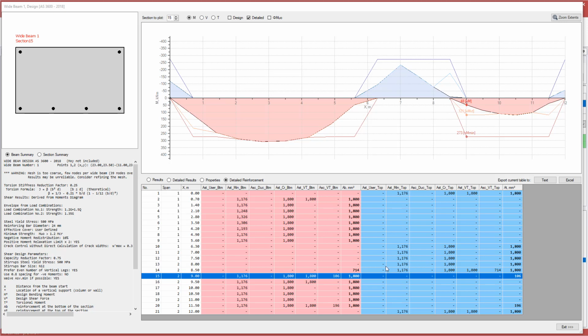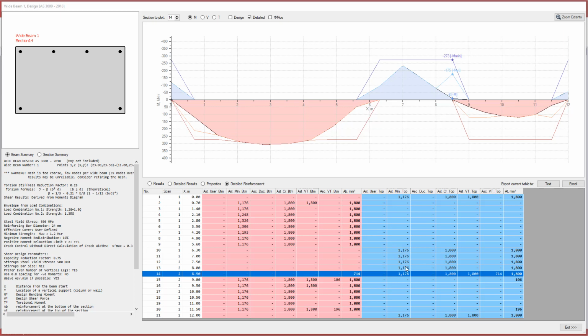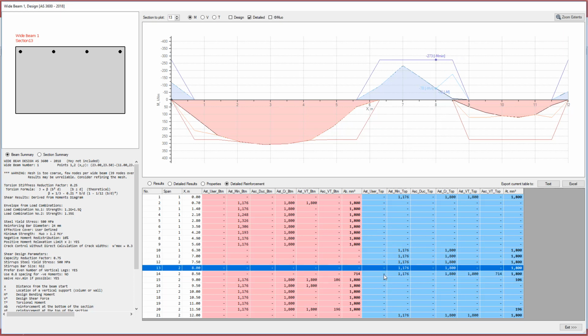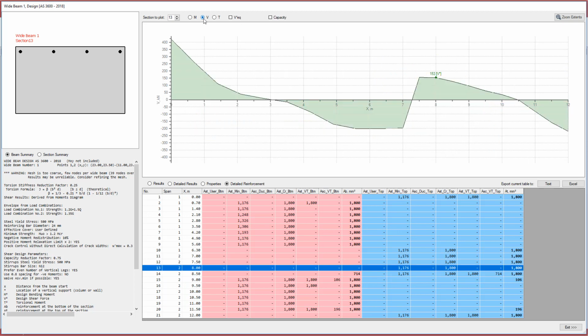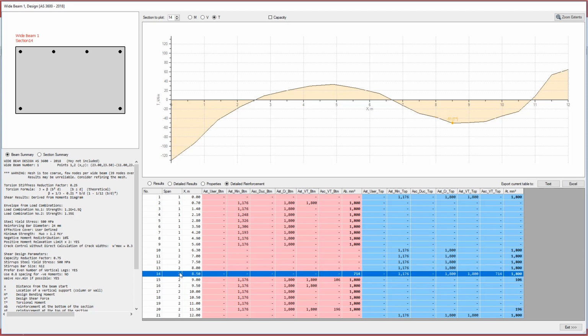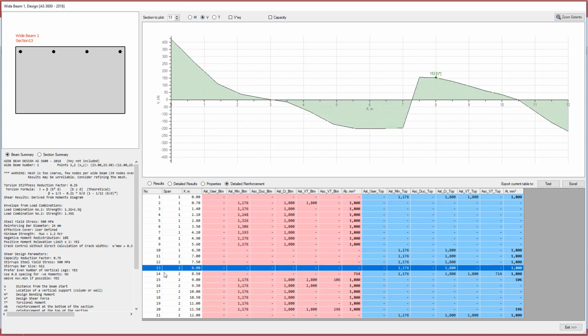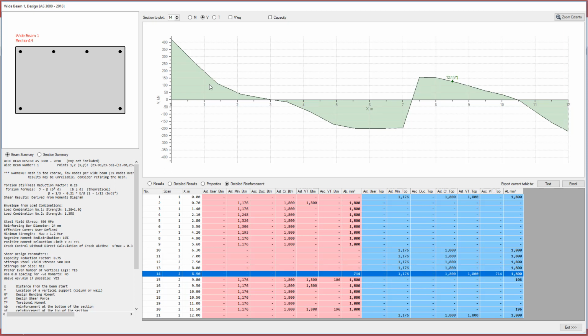And one final point that we'll look at, which also has some seemingly strange results which we'll try to make sense of, is point number 14. At point number 14 we see a spike in the MVT value, which at 13 is not there. If we look at the shear and the torsion, point numbers 13 and 14 are similar. Point number 14 has larger torsion, and the shear is a bit less in point number 14. If we look at the equivalent shear force, it's almost the same between the 2 points.